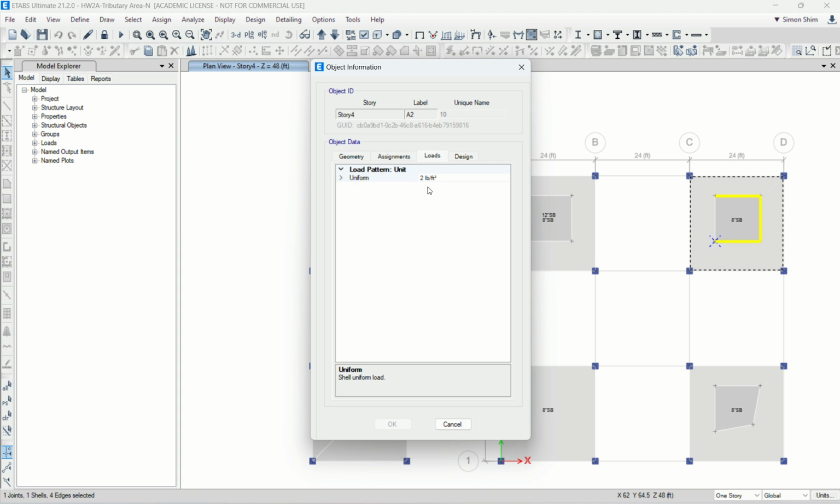I give you this method since ETABS offers it, because I think they got a lot of feedback, so they built this type of feature. Before, they didn't have this feature, so I needed to use an average area and assign it. Otherwise you're going to miss some loading, right? This is another step. At this point, this is not an engineering matter, just common sense. We have a requirement to address the higher load, but currently we model and draw one big plate.